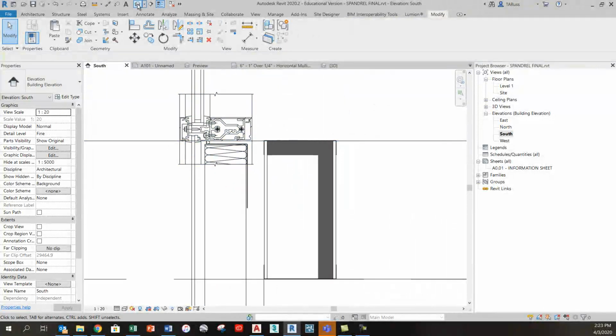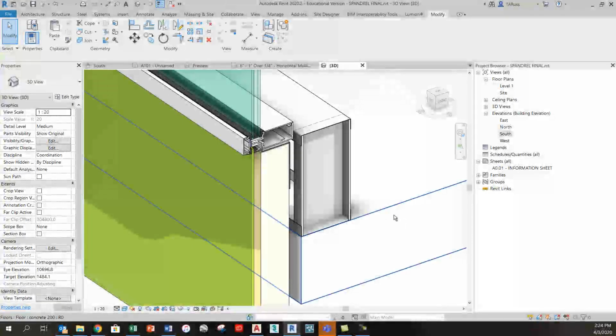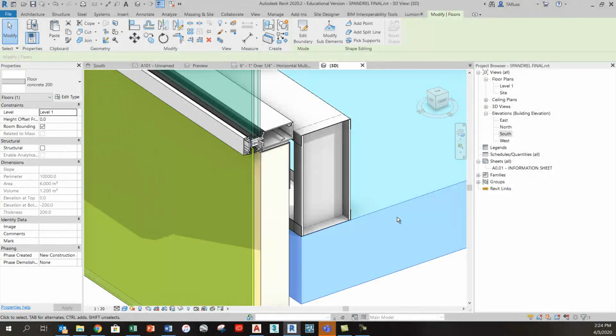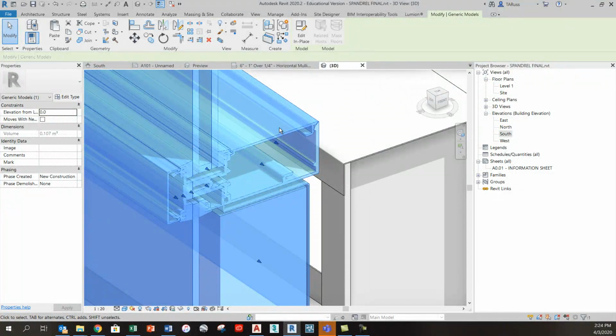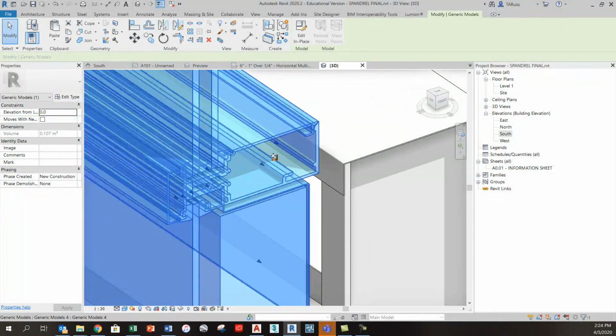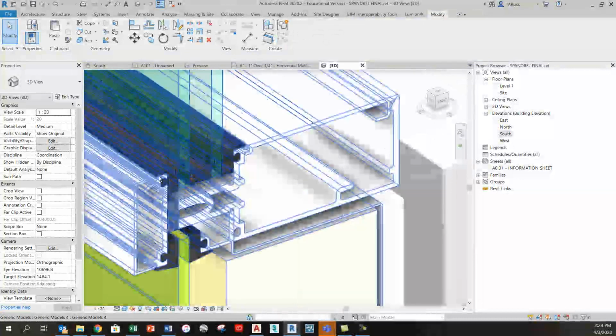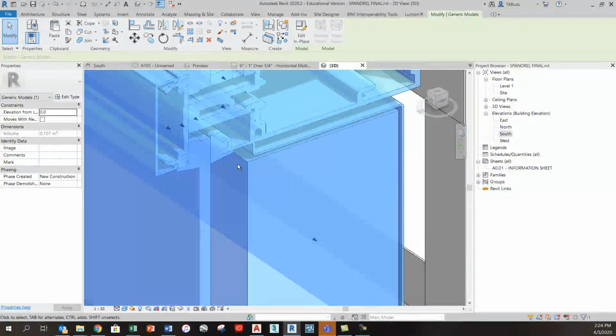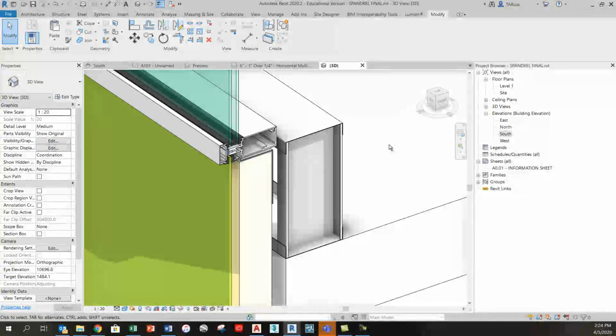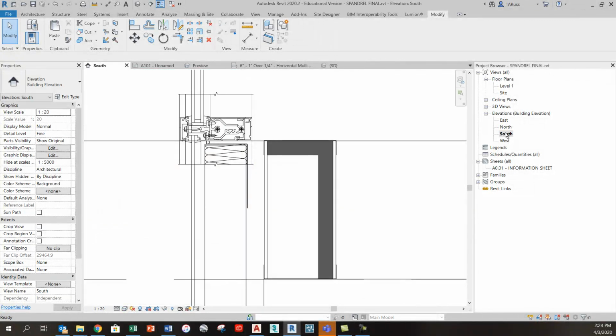So that gives me, as you can see from the 3D view, my concrete slab, which of course was just a common generation method for generating the floor in Revit, and then I added the steel stud tracks, and then that long process of using the details that I had from the website to generate the extrusion profile for the mullion and all of its bits, its gaskets and seals, and then of course these glass panes, and then the spandrel panel pane below. And that's all done. I'm not quite finished yet. There might be some elements here that you have to add or can add without necessarily having any 2D details.